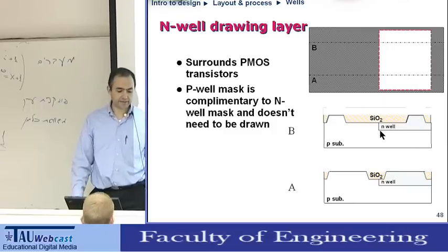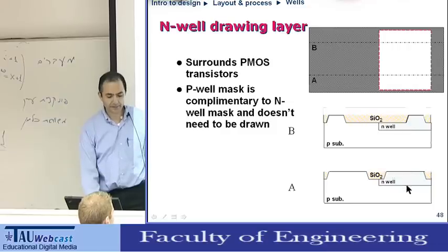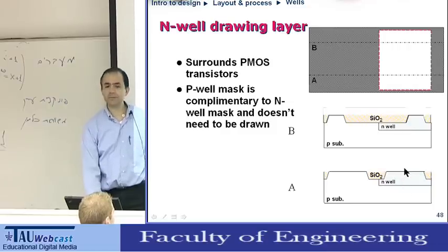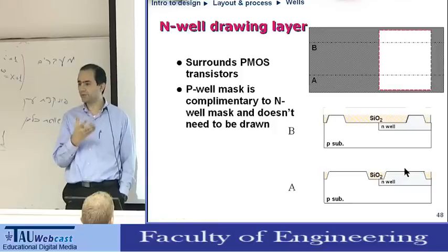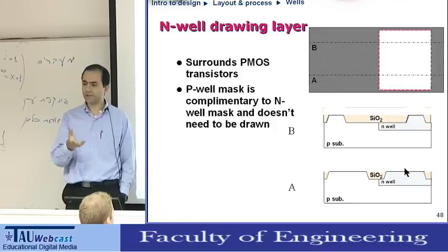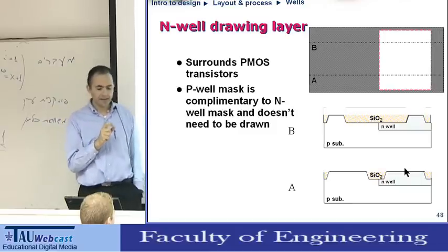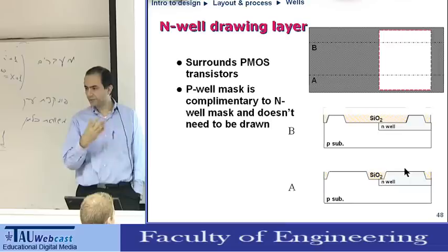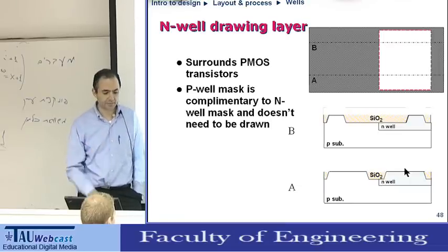Okay? And the amount of dopants will be determined by the dose of the implant. So the dose and the depth determine the doping level. Again, it will have to get annealing, but after annealing, it will determine the doping level.